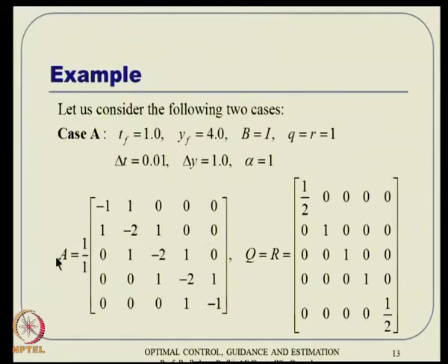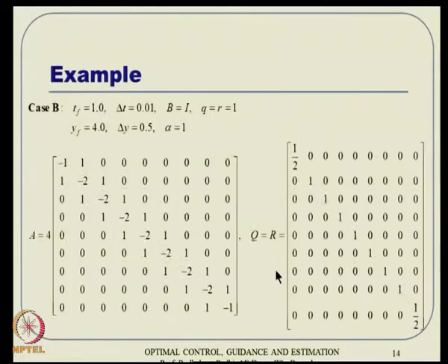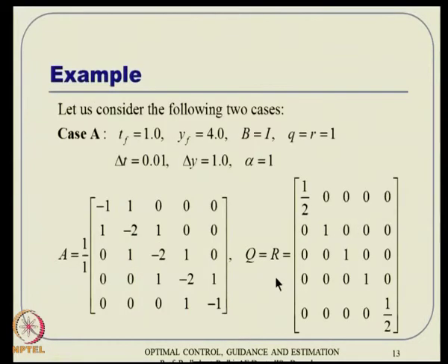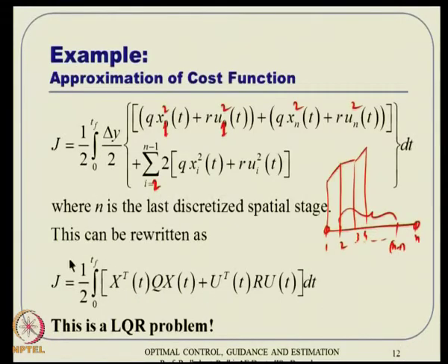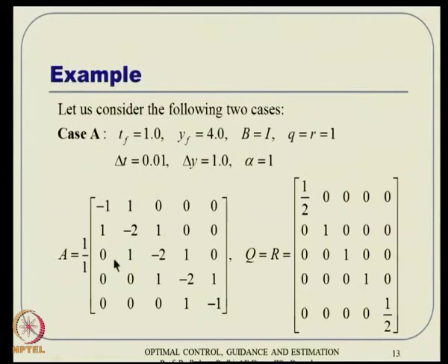So we have got the A matrix, we have got the B identity, we have got Q and R. We incorporate the LQR function and solve it. Remember, MATLAB LQR is geared towards infinite time. Here you are talking about finite time LQR, so you have to do a little bit of coding. The final SF equals 0 in this case, because the outside term is not there. So PF equals 0, but P dot is the Riccati equation, and you have to integrate it backwards from 1 to 0 and then implement it forward.